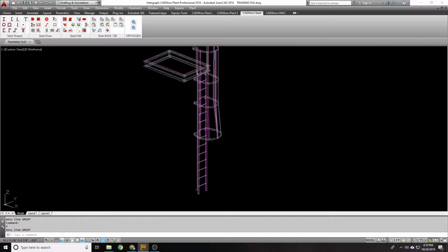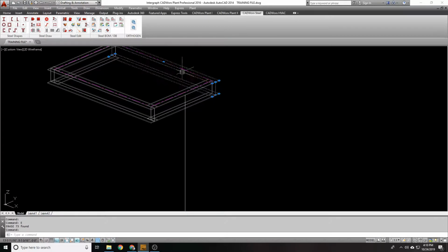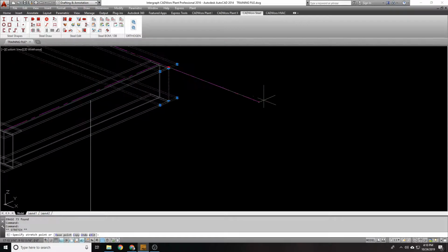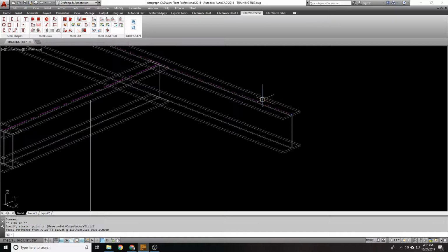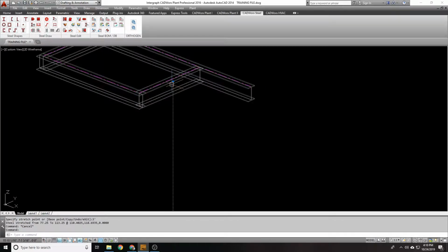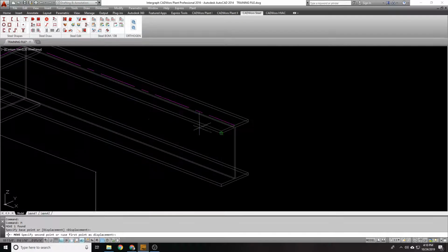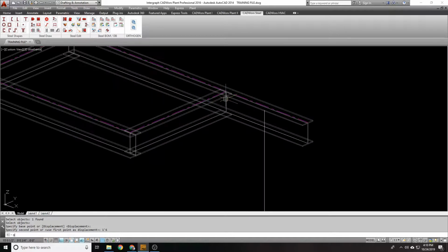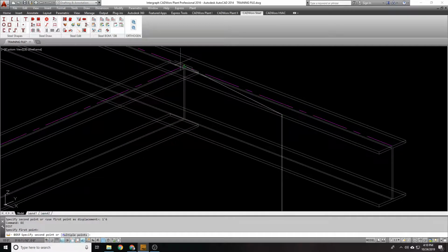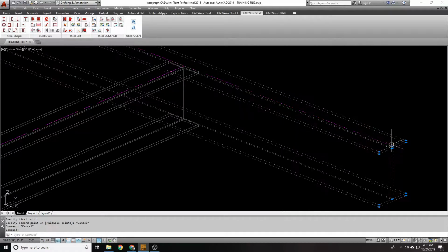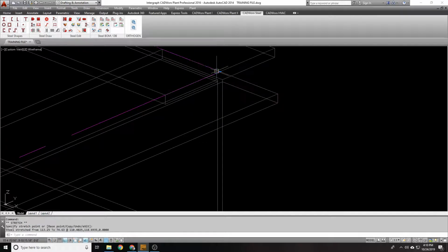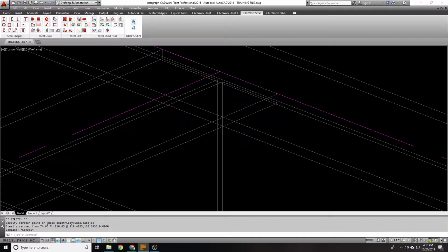All right, last thing is we'll do an example of a side step ladder. I'm going to fake in a cantilever here of 3 feet, and I'm going to put this line over here and move it back 1'6". My company has a standard of a maximum of 1'9" from this point to this point, which is the side step of the ladder. And right now, I think, let me do it 3 feet from here. That way we get a nice even dimension.